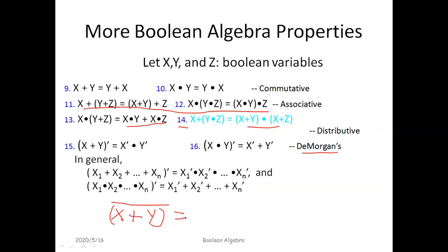So x plus y inverted, in De Morgan's laws, this means you have x, then the plus is converted into a dot, and you have y. Then what happens? We had a long bar here covering everything. But the moment you change the plus to a dot, this long bar is broken and you have those bars appearing. That's how come we have that statement.